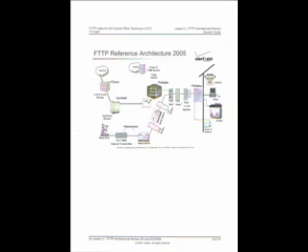Here's an example of an FTTP network from start to finish. This is a rough block diagram displaying how voice and data are connected to the OLT and combined with video at the wave division multiplexer. The signals are combined and transmitted over one fiber. That signal is then split and transmitted over 32 fibers. Each of the 32 customers has an ONT to demux the signal and separate it back into video, voice, and data.